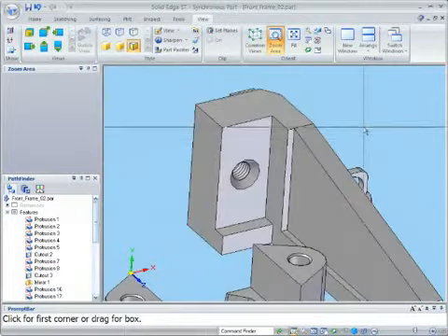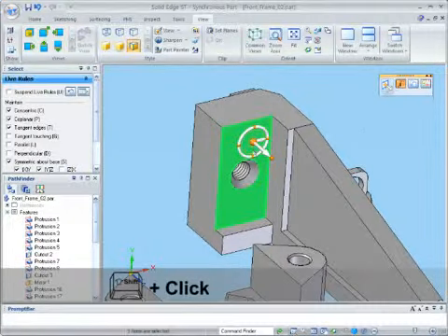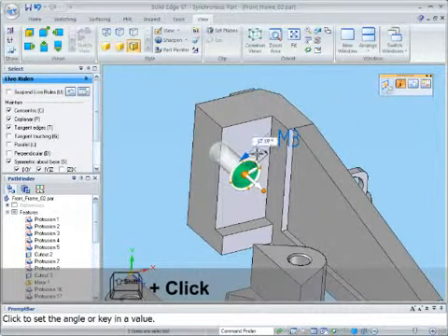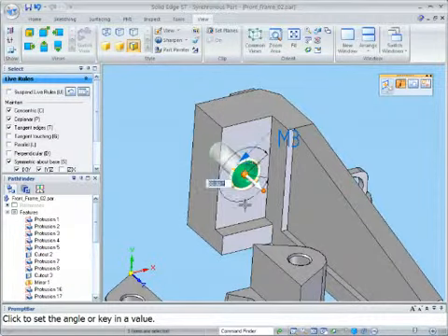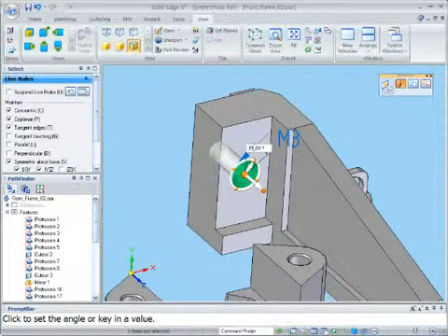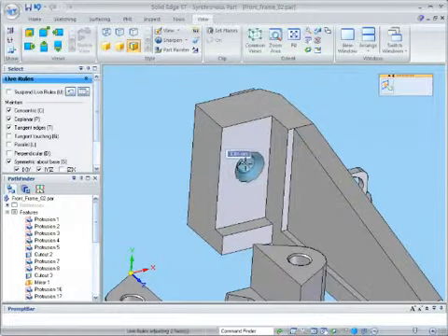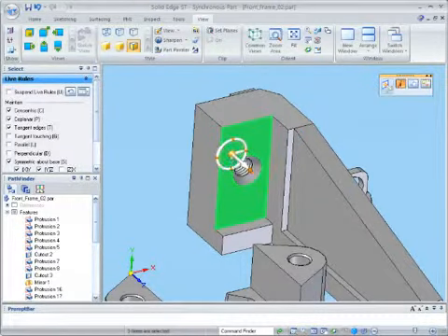To accurately rotate the steering wheel around its axis, shift-clicking on the torus allows it to rotate. Using the Tab key moves focus to the dimension box, allowing you to key in a precise angle. Mouse position can also be used to infer the opposite angle if you want. Now with the steering wheel rotated to the required angle, you can use it to make your intended modifications.